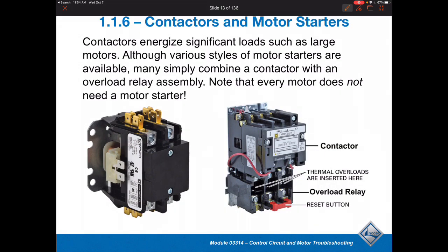All right. So contactors and motor starters. And of course, one of the things that we had discussed was, well, what's the difference between a contactor and a motor starter, or what's the difference between a contactor and a relay? Well, when we talked relays, relays typically are going to be limited to that, let's call it 15 amp range at most, as a general rule. Usually you start looking at contactors when you start exceeding 15 amps.